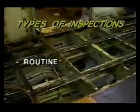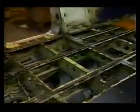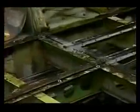Routine corrosion inspections are performed at times when other maintenance activities have made accessible areas of the aircraft which are not normally accessible during daily or pre-flight inspections. Routine corrosion inspections require the removal of panels, access plates, and removable skin panels to thoroughly inspect the internal portions of the aircraft.